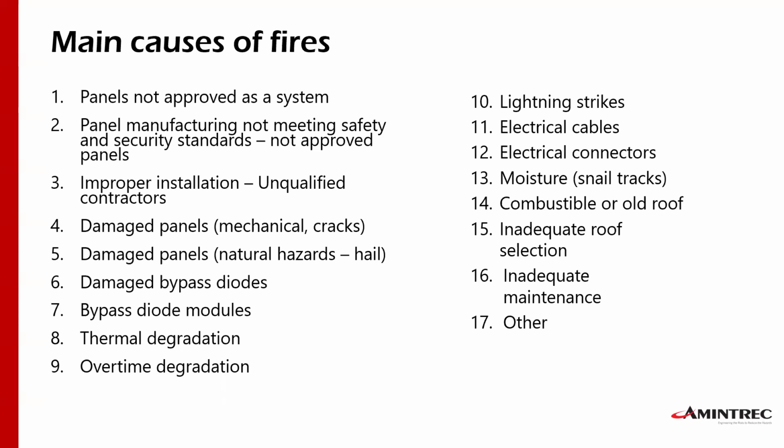Panel manufacturing not meeting safety and security standards. That's basically not approved panels. Improper installation. That is a very critical cause of fires due to unqualified contractors. Damaged panels due to mechanical stress and cracks. Damaged panels due to natural hazards, for example, hail, snow, windstorm, and also earthquake. Damaged bypass diodes. That's also an important cause. We will see that. And also bypass diode modules. We will understand why those two are important.